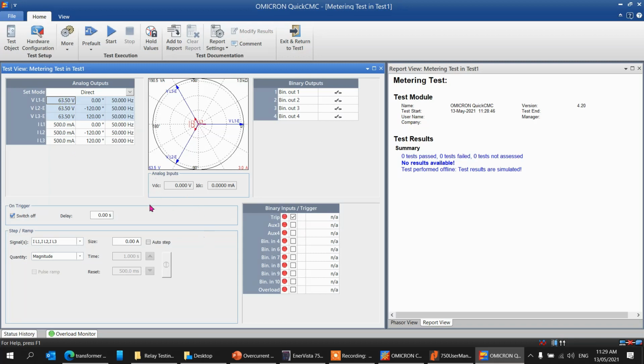Then you run. So how do you verify phases if you put everything equal? Come again. How do you verify the right phases if you put all the magnitudes equal? You can also change this one. It's part of the process. For example, you put 250 and then a smaller one, 150. It's up to you. Also you can verify that using your power formula. The power formula will check if the connection is correct.